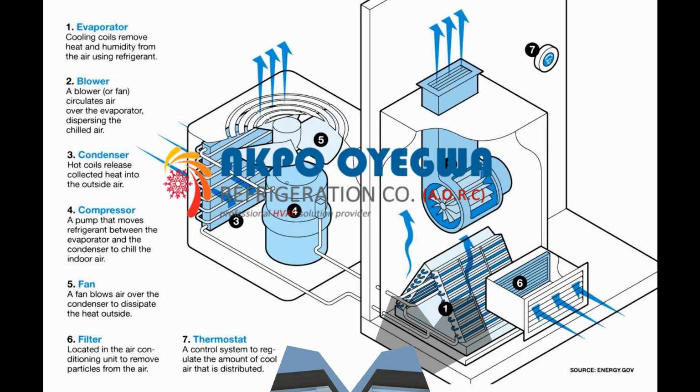An air conditioning system works by using a refrigeration cycle to cool and dehumidify the air inside a building. The basic components of an air conditioning system include a compressor, a condenser, an evaporator, and an expansion valve. 1. The compressor compresses a refrigerant, typically a type of fluid such as R22 or R410A, and turns it into a hot, high-pressure gas. 2. The hot gas then flows through the condenser, where it releases its heat to the outside air and condenses into a liquid.